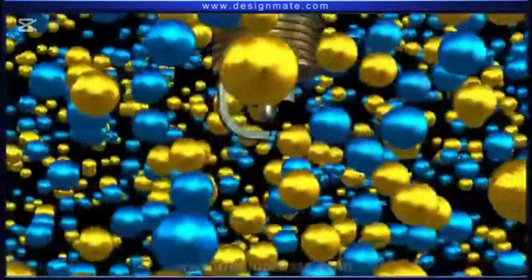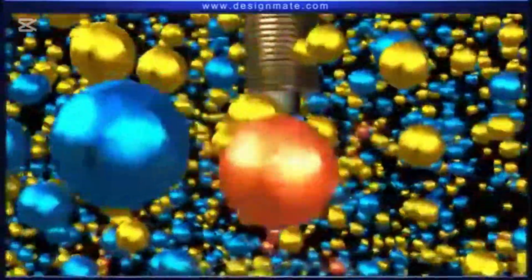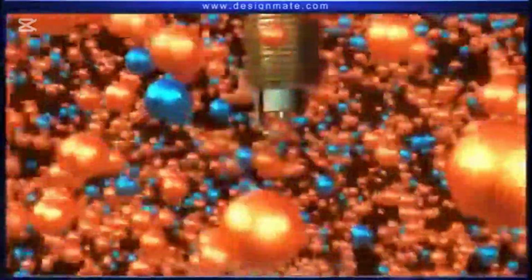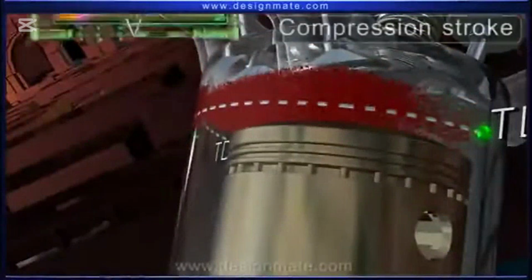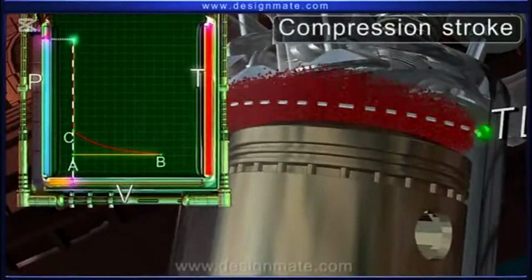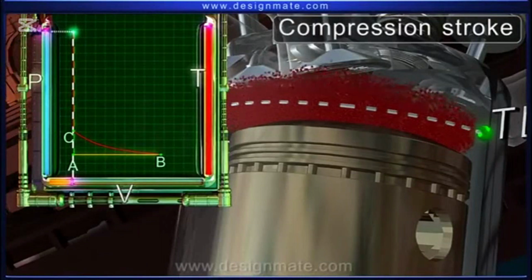Just before the piston reaches the TDC, the spark plug produces spark and the fuel explodes. Rapid combustion in the closed cylinder increases the temperature immensely. The pressure in the combustion chamber increases to a very high value, with almost no change in volume.